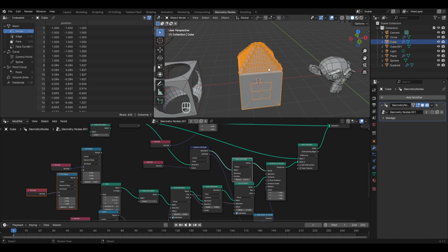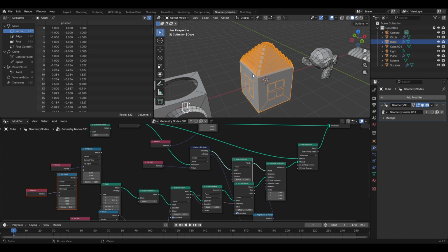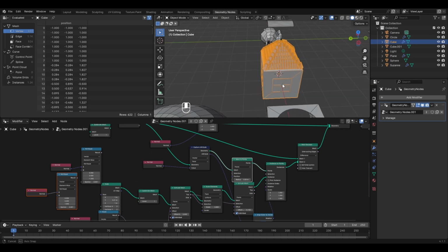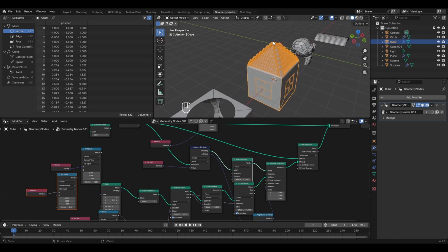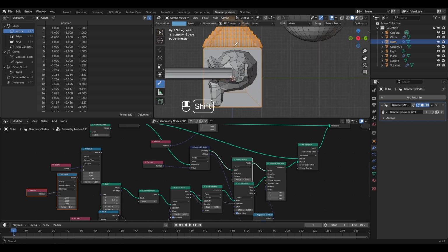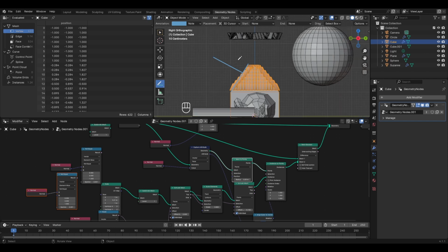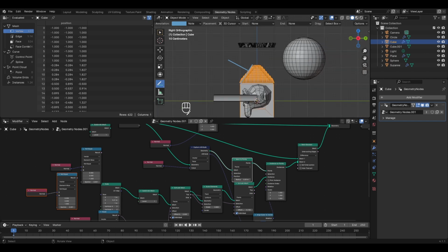Now another thing to understand here is that the normals of the faces where we have added these roof tiles are not perfectly in the Z axis, and that's because they're not straight like the other faces. You can see that they are slanting like this, and as a result, if I take the Annotate tool and change it to Annotate Line, and if I go to the side view by pressing 3 on the numpad, then the normal of these faces will be something like this. You can clearly see that this is perpendicular to the face, however it is not lying perfectly in any of the 3 axes. As a result, when I connect these Compare nodes to the Mesh to Points, it will basically mean that these faces will also be included.